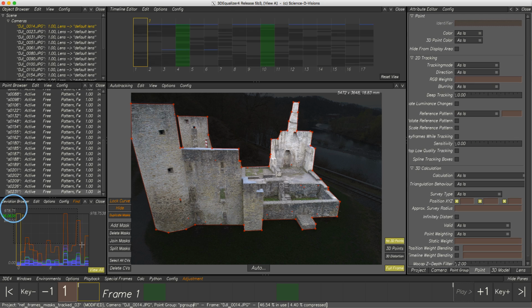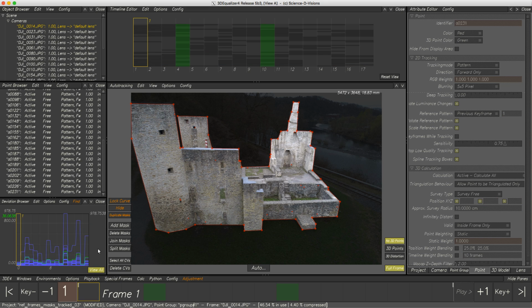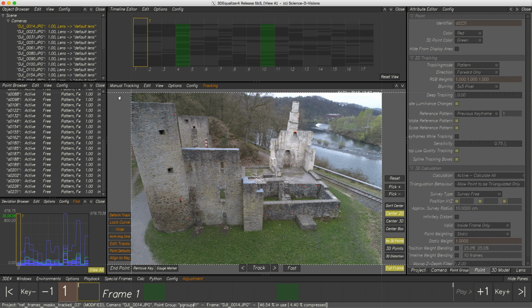Now, simply deleting points purely based on their deviation is not entirely wrong and would improve the reconstruction quality. But points with such a huge deviation might influence other points, and by simply deleting the highest deviations, we might accidentally delete actually good track points. So there might be a better and more reliable way. Also, like in sequence tracking, there's a nice feature helping to detect such points.